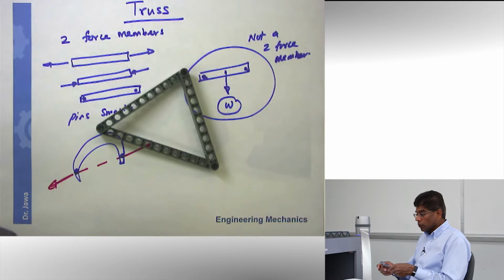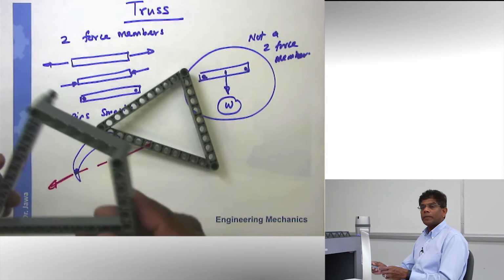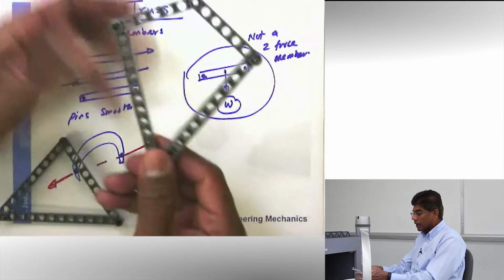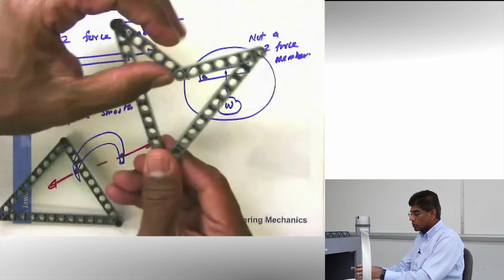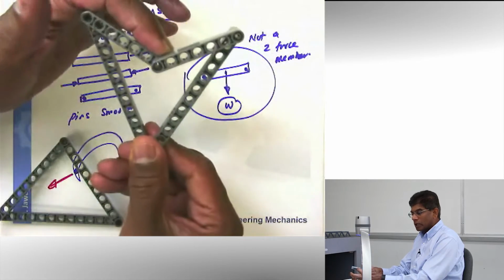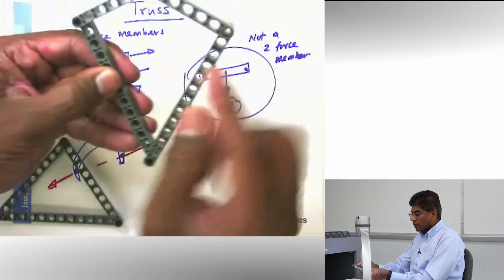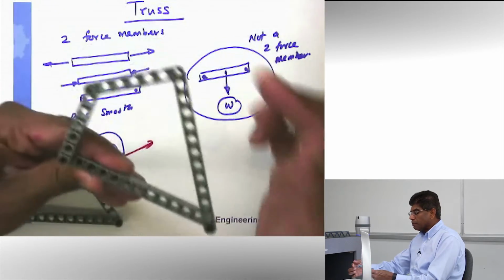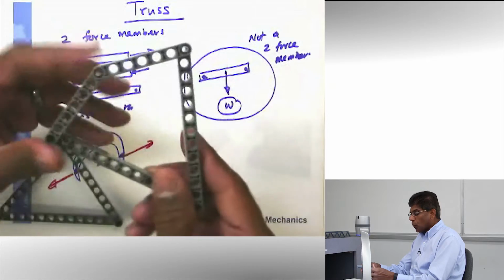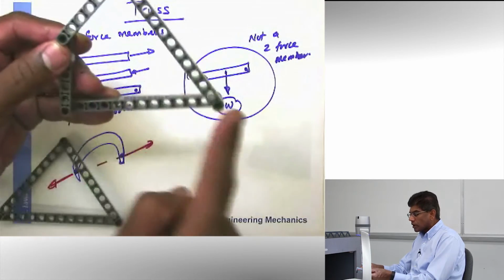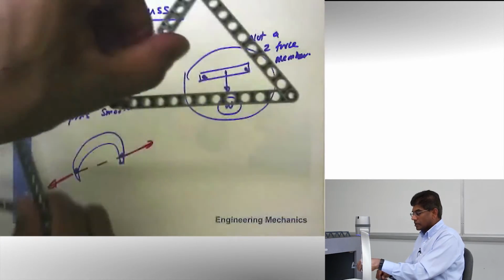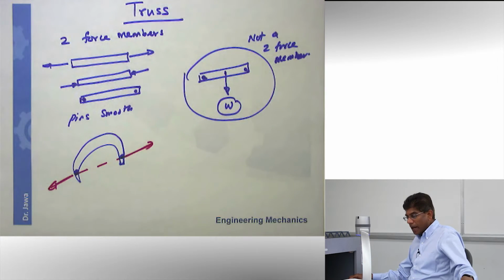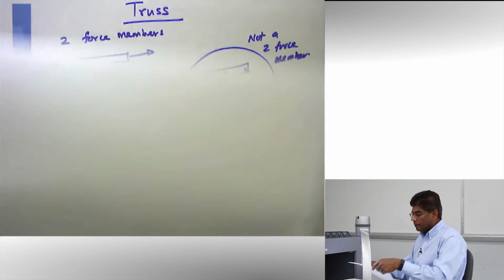And for those of you who think, how about we make a structure with 4 members? If you look at 4 members here, clearly if I give a push here, this is losing its geometry. It actually collapses. So when you have 4 members like this, what you have is not a structure, it's a mechanism. All right? So if you want to make this a structure, you need to put in a cross beam, making it a triangle structure. So if you look at trusses, most trusses are made with simple triangle members.